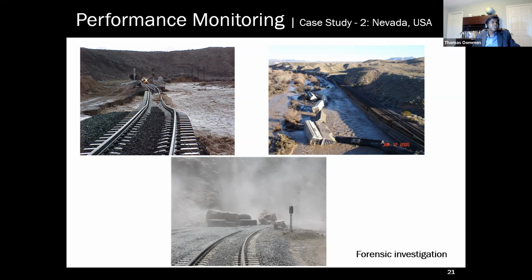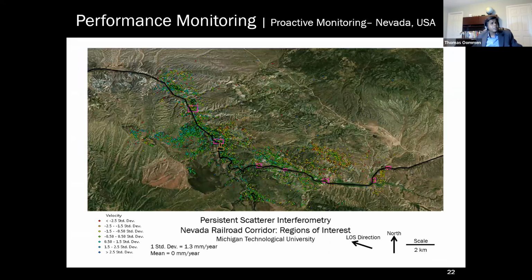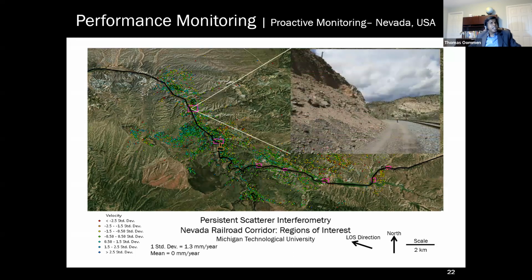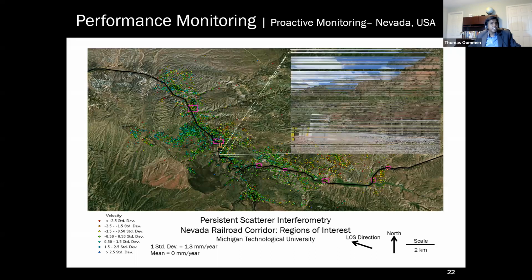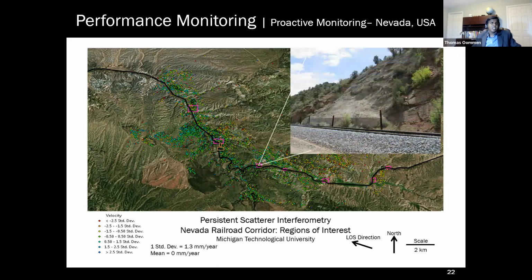Some of the slopes have become unstable. So now the question was where all there are unstable slopes along this track that we can actually identify. So we did an analysis all along that corridor to identify areas that are vulnerable, and we were able to identify those areas for them. Some of the areas, based on our recommendation, they actually fixed, so you can actually see some of the slopes where they have shotcreted based on our recommendation, because those areas were starting to fail and creating trouble.